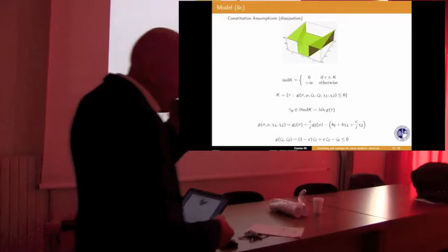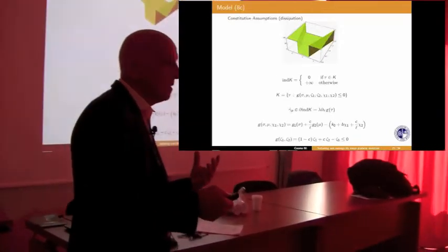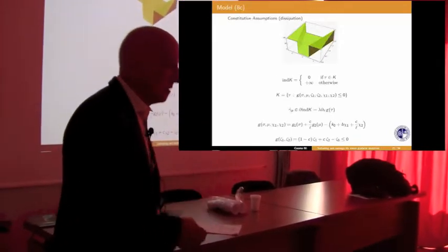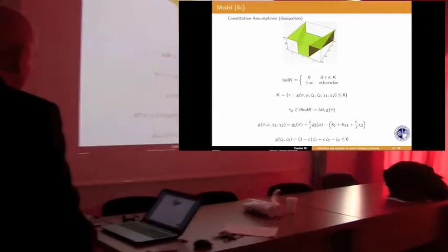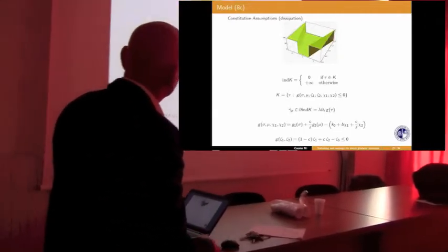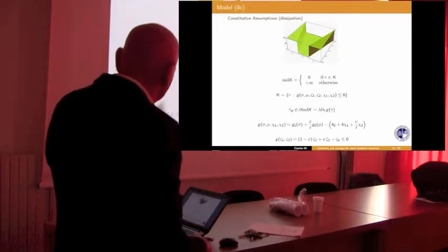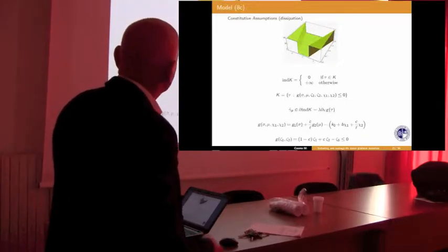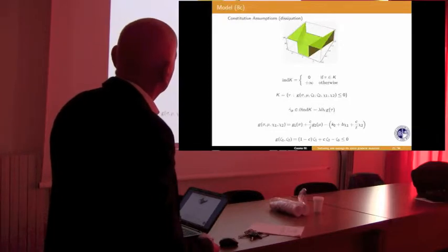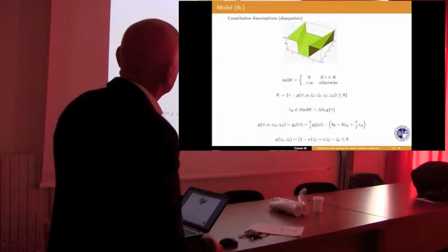You can imagine this domain in a generalized space of all forces. There are two examples of this function. This would be a yield function in the 1D case for plasticity, that couples the stresses, hyperstresses, and hardening variables.